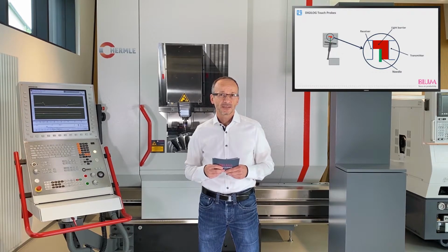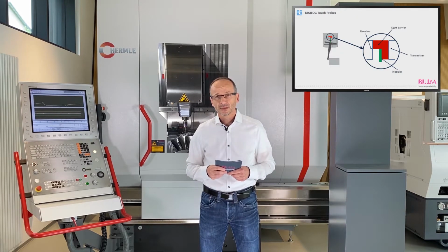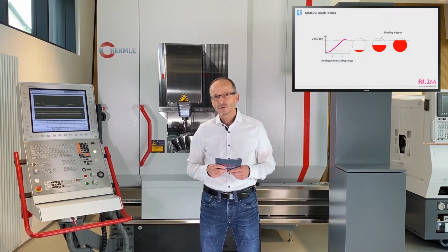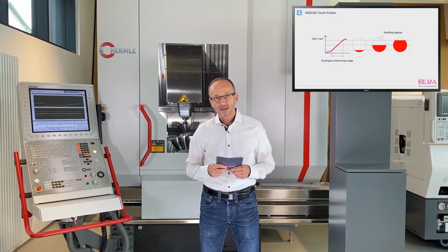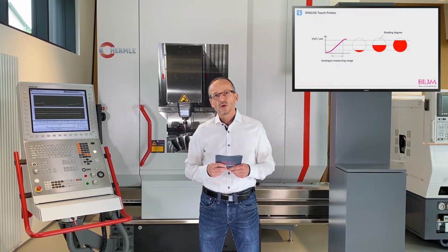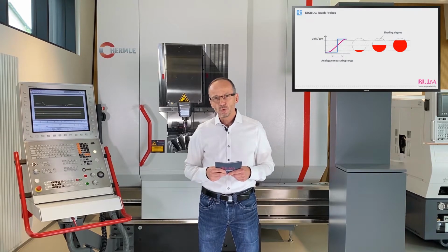This functional principle has the fundamental advantage that it is completely wear-free. This applies to all Bloom probes, regardless of whether they work with or without DIGILOG technology. It also offers a further and decisive advantage. In simple terms, this means that we can record the degree of deflection of the probe in the micrometer and submicrometer range. This enables us to evaluate a workpiece not only point by point, but we're now also able to scan a surface. And during the scanning process, we can record the deviation of the actual profile to the target profile. To understand this better, let's watch a short video.